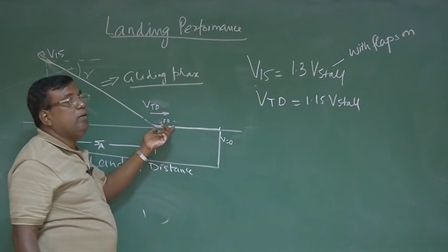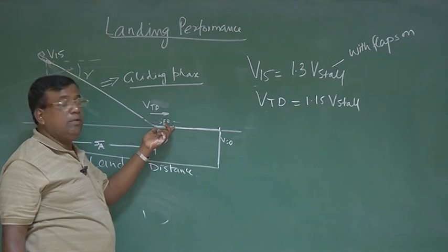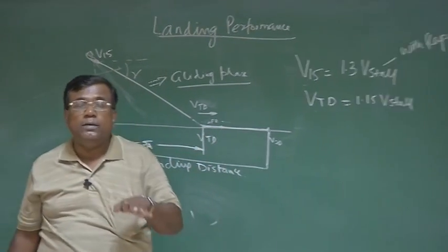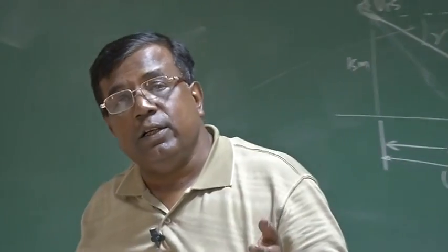So this also I can calculate. We have done it for takeoff also, in a similar way. And here we have applied brake. In the takeoff, we found acceleration and took average acceleration, but in landing, we will take average deceleration, so that we can easily use V square minus U square equal to 2AS and find the S.